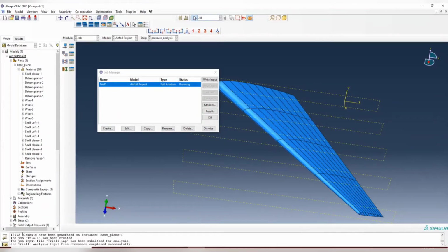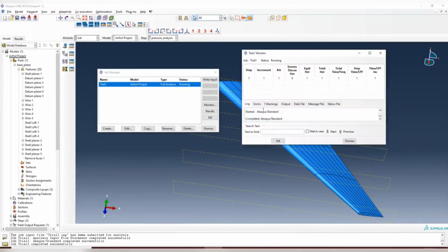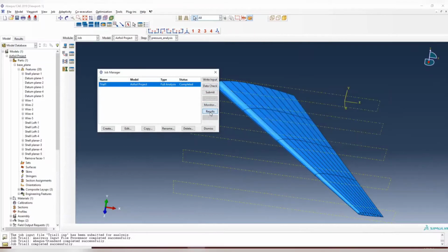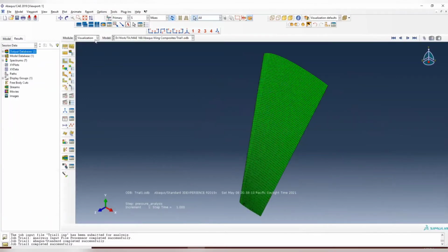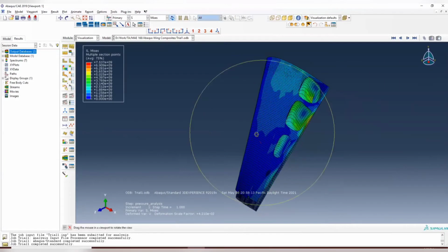This should not be a very large number. If it is too large for you, you can decrease the mesh size. And it should be relatively fast. This only takes like 30 seconds or something. Let's see the result. So here, long click this one and select plot the contour on both shape, deformed and undeformed.